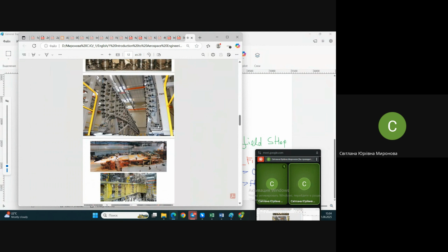Actually, these jigs, by the classification of jigs and fixtures, are mostly fixtures, to be frank, if we follow their own classification in English. But as they are only for locating and temporarily clamping, they have no devices for directing, for guiding the tools while assembling. Tools will be drilling, drill bits, I mean. The processes of drilling, the processes of riveting, they are fulfilled immediately in these jigs.